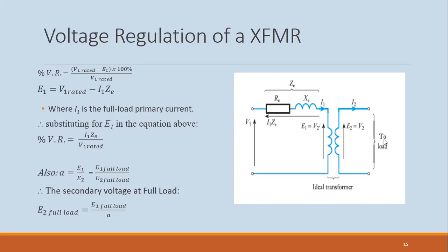So when the voltage is starting to get low, it allows more of the primary turns to be connected to the supply voltage, right? So as we see now, the voltage regulation will be about 5.5%. We would actually have to raise the primary voltage by admitting more turns to be connected to the supply voltage.